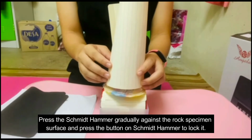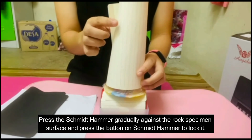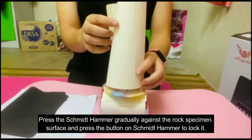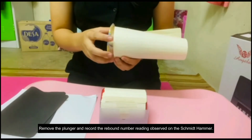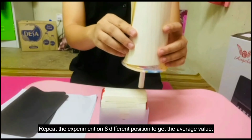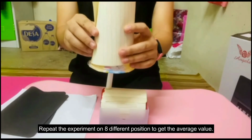We press the button on the Schmidt hammer to lock it, and then we can read the reading. Remove the plunger and record the readings observed. Then we repeat the experiment at a different position to get the average value.